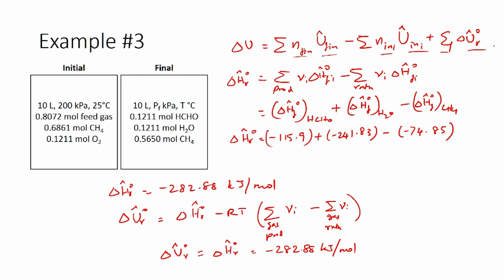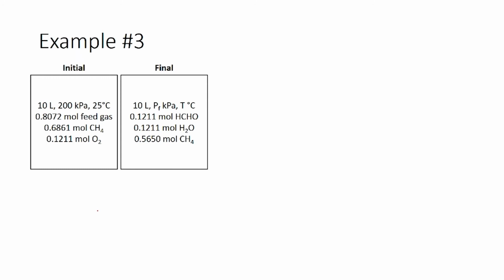Now that we have all these values, we can plug them into the equation for the heat balance, which is Q. In the problem statement we have been told that heat is supplied by an electric coil at a rate of 100 watts for 85 seconds and then it is stopped. So, the amount of heat supplied would be Q equals 100 joules per second times 85 seconds, which is 8500 joules or 8.5 kilojoules.